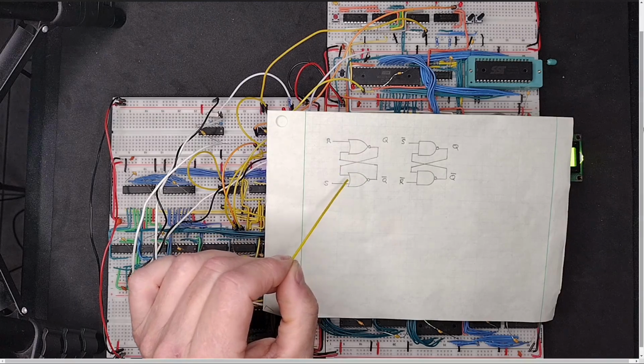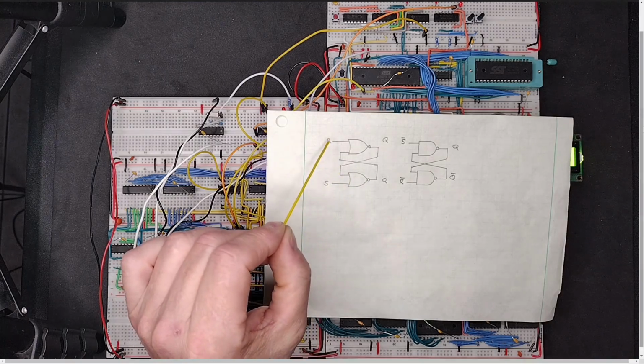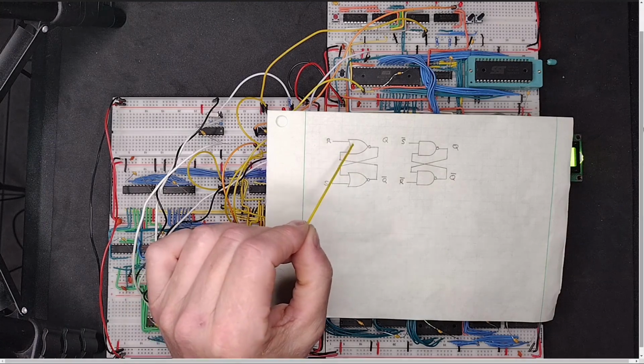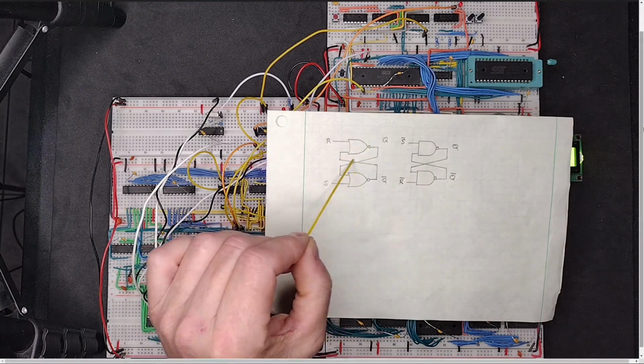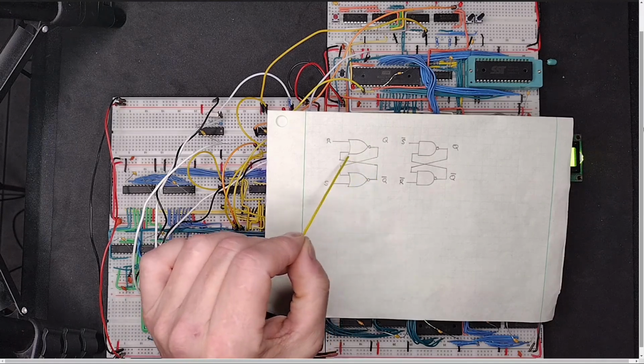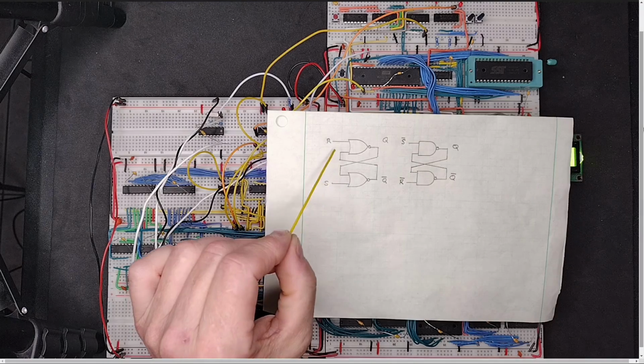And then, likewise, if you then were to turn the R high, flip the R from low to high, then it'll reverse it, because now this is high, so the output of the NOR gate is low. So this is low and this is low. So the output here is high and so forth. So S to set, R to reset.